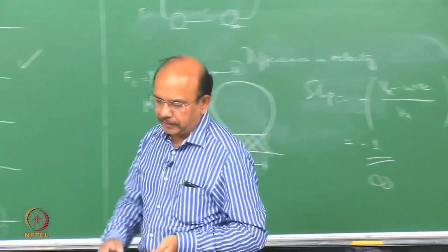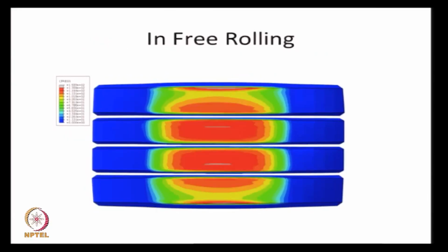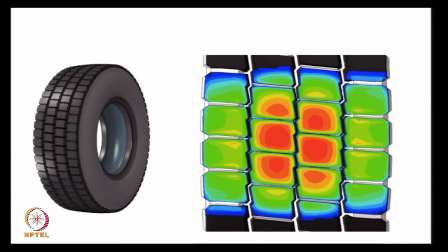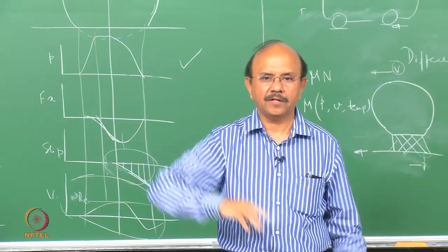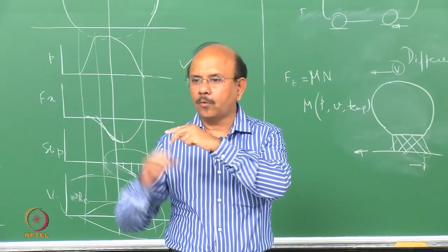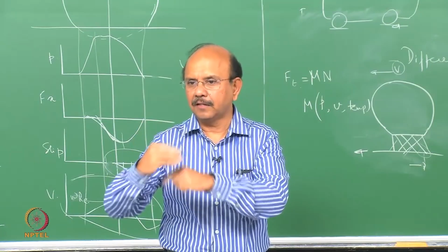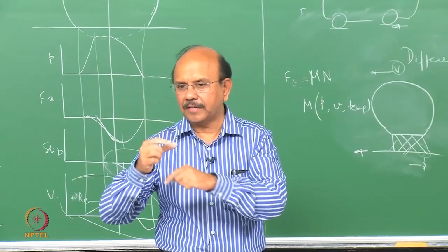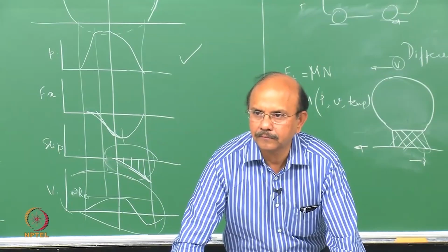These block tires are prone to what is called heel and toe wear, where because of this distribution of pressure, you would see that each block, one side of the block has one wear rate, the other side another, and so on. So there's uneven wear even in those blocks, which gives rise to heel and toe wear. Okay.